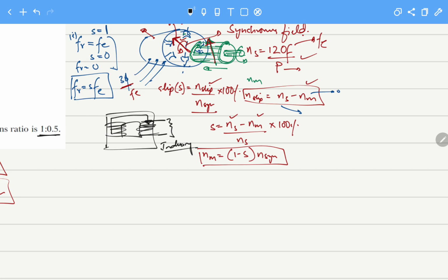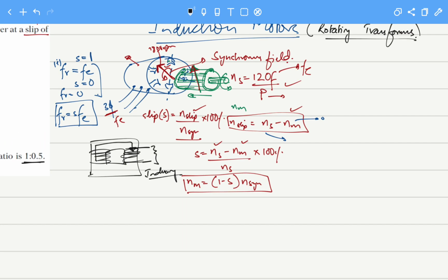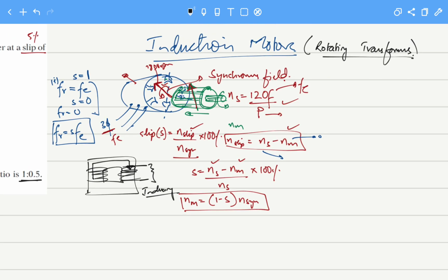If we closely look at our induction motor, the scenario is very similar. The stator windings produce a flux, and this flux cuts the winding in the rotor and induces voltage. That is why the principle of induction, similar to transformers, also exists in induction motors.